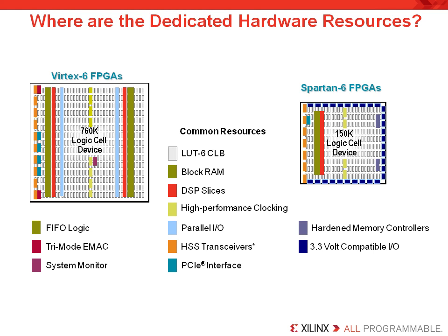You should be in the habit of making area constraints that make sense for the placement of your dedicated hardware. Also note that the placement of dedicated hardware varies considerably by device family and density. Area constraints that work for one device will need to be altered if the design will move to another device.